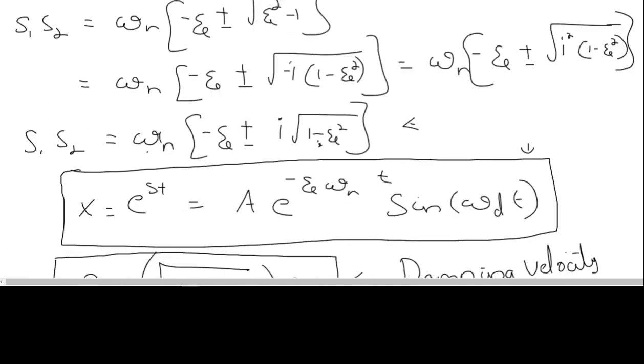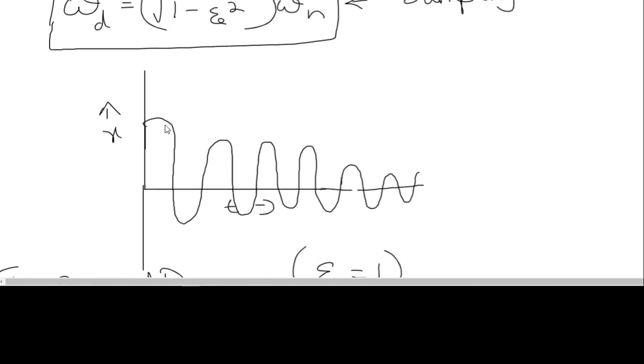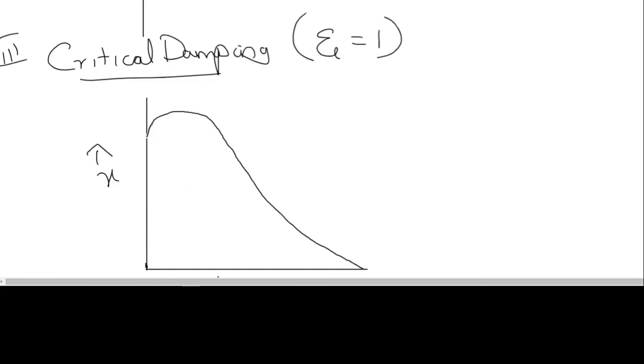And second one is under damping. That means you are getting a continuous vibration without ever reducing it to zero. So you will be going like in a pothole, and the effect of that pothole will be for more than half a kilometer. So you will be vibrating continuously because your damping is not sufficient to absorb.